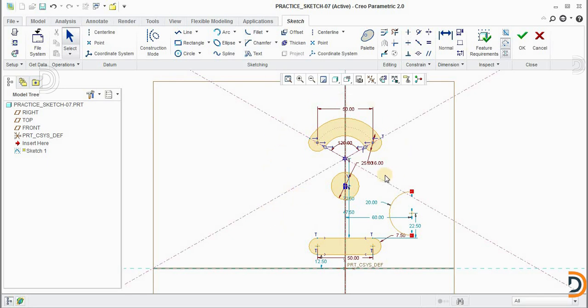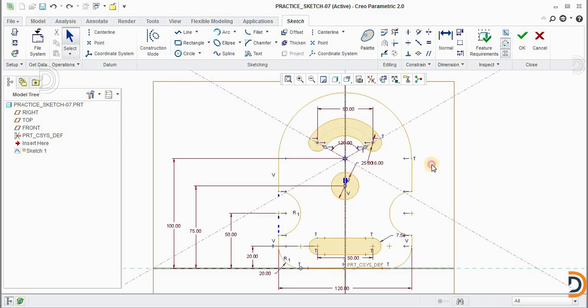So after deleting the whole loop, we can see that here is one arc. Means we can say that this arc was overlapping geometry. So for the time being, I will press Ctrl Z. Now here we know that this arc is overlapping at this location.